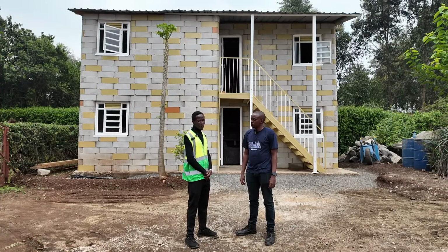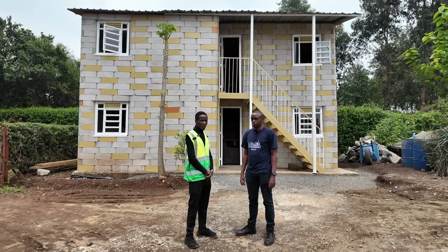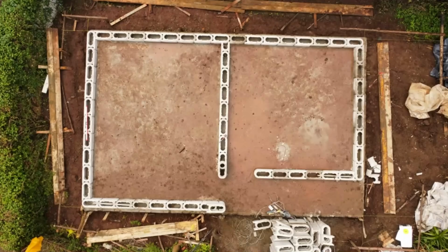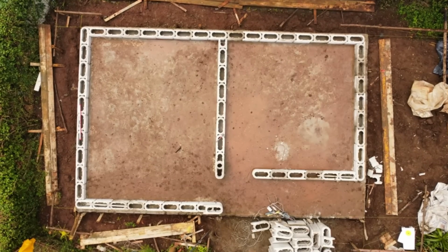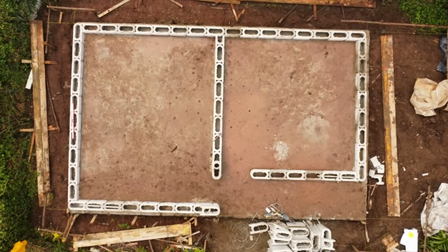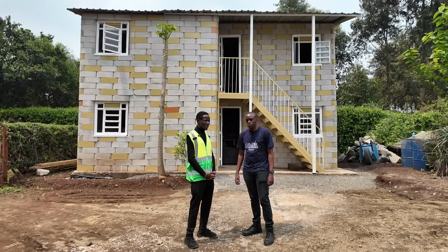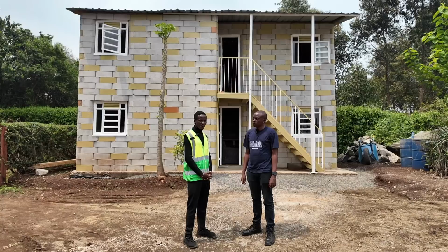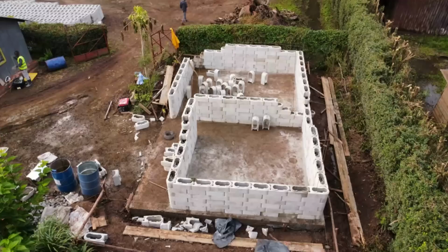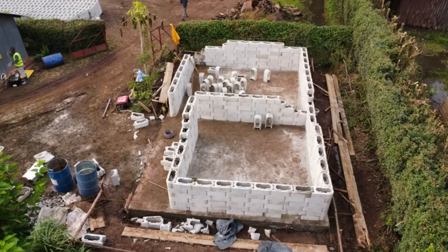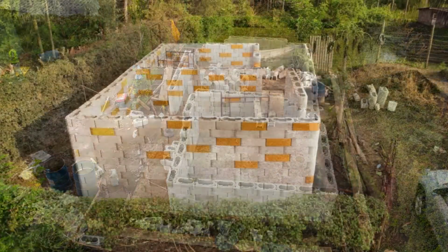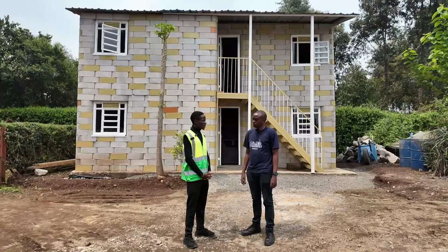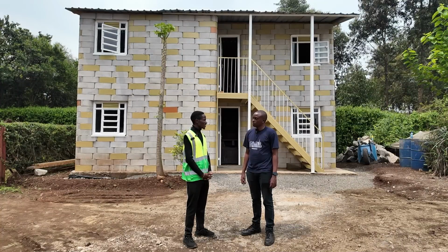And afterwards, when you start doing your walling, for the first course you have to ensure that the slab, that is the ground floor slab, is very level, because the twist blocks are a standard product. They are very standard, all of them. So if you mess with the leveling, you will mess with the entire walling. So you have to have a proficient mason who does the leveling. For the first course, it has to be perfect. Then going upwards, that is how you reduce the mistakes and the blocks fit in properly.